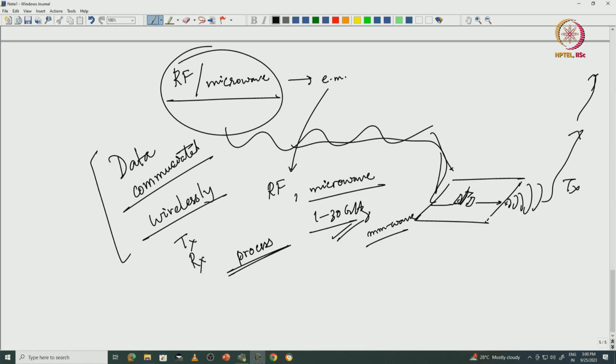For instance, when you have so many applications running in a cell phone, your battery will be drained very fast, because the RF power amplifier, for instance, guzzles up the battery very fast. So the circuit designer has to place extremely stringent constraints. The device has to have certain linearity, efficiency, power, gain, etc., so that it gives all the functionalities you need without draining the battery too much.